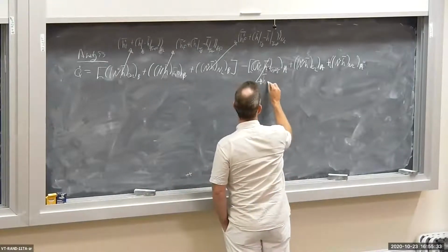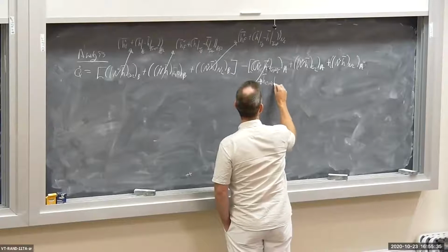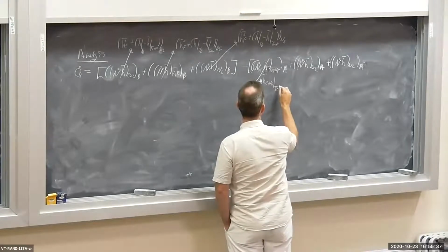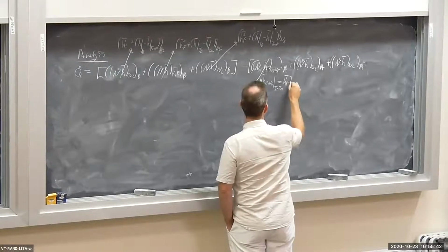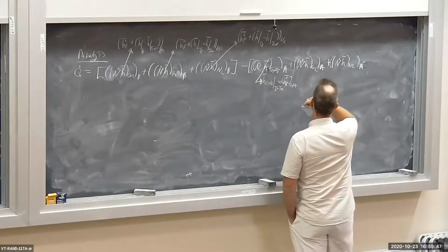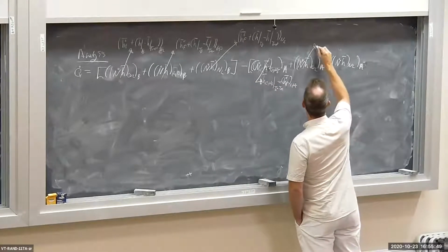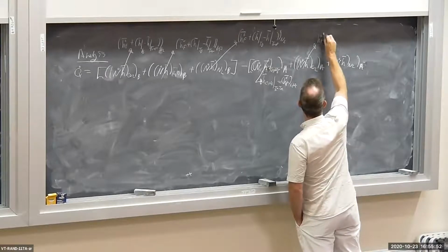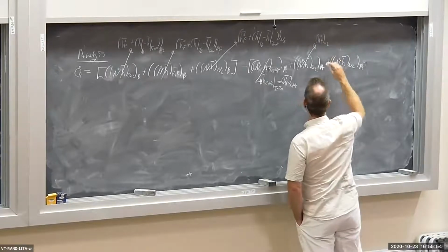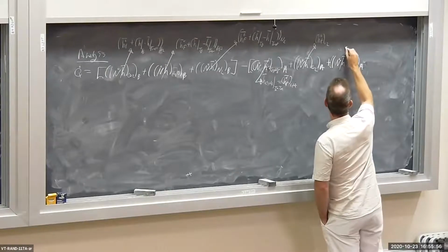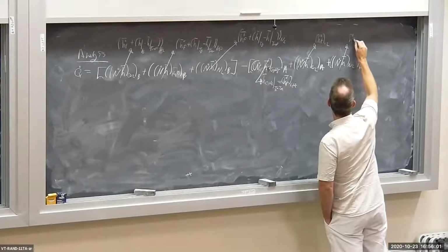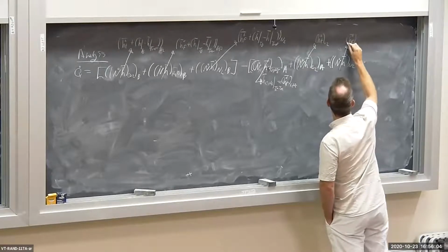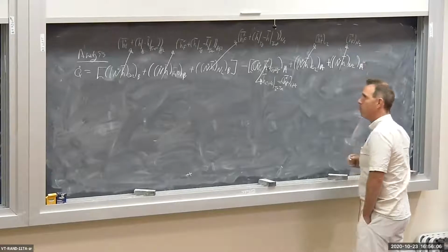So H bar of the C3H8 evaluated at TA equal Tref is equal to the enthalpy of formation for the propane. Same thing for the O2. This is the enthalpy of formation of O2 because we're at the reference temperature at the inlet, and so is H bar for the nitrogen at the inlet. It's the enthalpy of formation for the nitrogen.